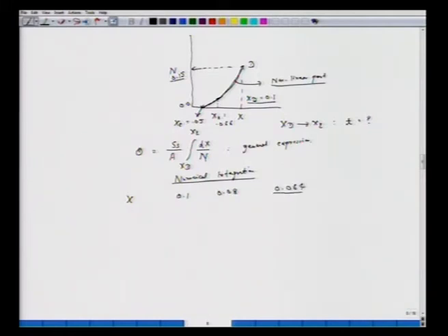We have to go till it's below X2, which was given as 0.066. We start from 0.1, which is your Xd. For this, the rate in 10^-3 is given as 0.15. These are the data, 0.07, 0.04. You are supposed to take as many data points in between as possible for a very smooth curve here.